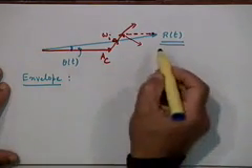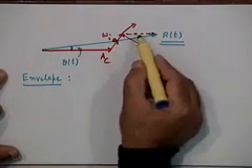By envelope I mean the length of this vector, right? The amplitude. The amplitude is what will be important when we are looking at the output of the envelope detector, right? Because the envelope detector will produce an output proportional to the instantaneous amplitude of the carrier wave, right?